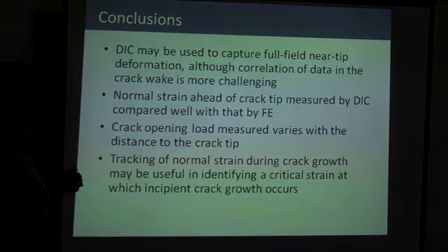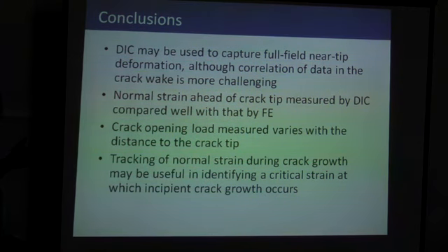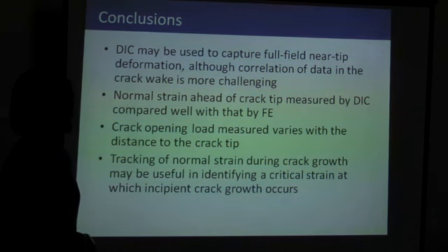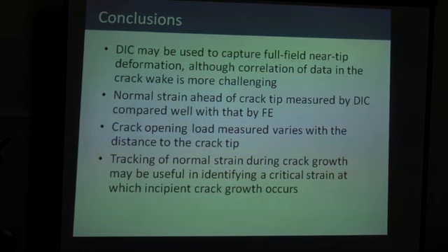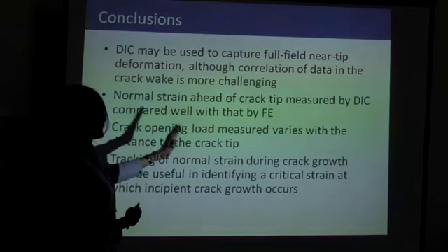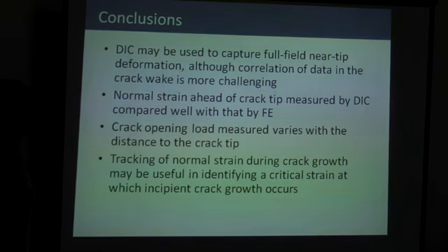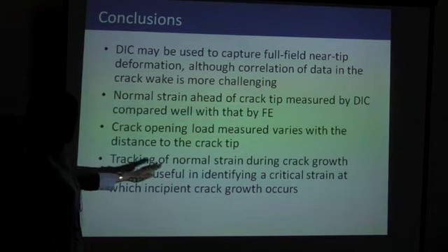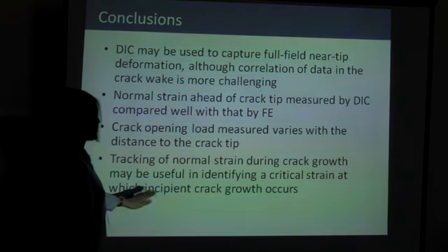So to conclude, we say we could use DIC to look at the strain field, but to correlate the data in this way is quite difficult, or at least the resolution is for what we get. The normal strain at the crack tip seems to compare okay for the higher load level, but we don't know about the crack opening influence on the strain field ahead of the crack tip. And we think if we track this normal strain, we might have some idea about the